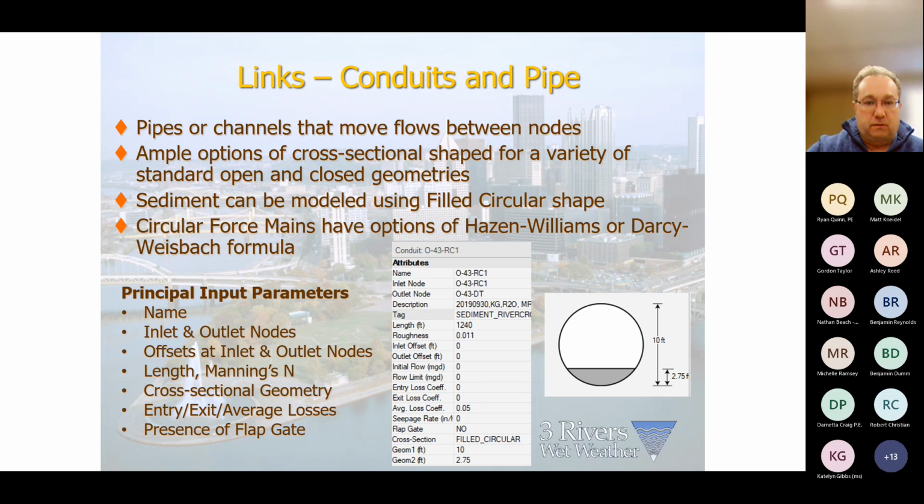So the flap gate's not on the outfall itself. You can put it in many different places. So yes, you can put it on the outfall. That's a place. You can put it on a pipe. You can also put it on an orifice, a weir. There's lots of different places where you can put that flap gate. If you put it on multiple things...